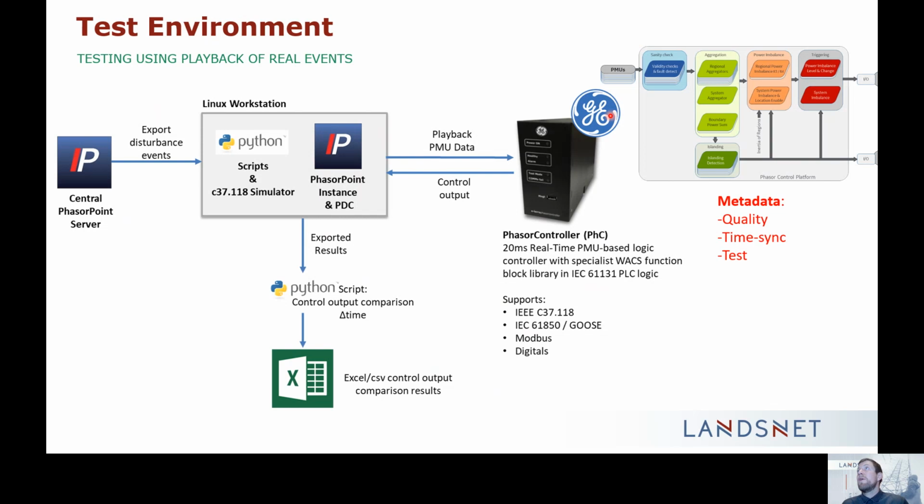And here's a diagram of the modularity of how the control schemes work, going through validity checking, fault detection, then the aggregation phase, islanding detection. The latest one, which I'll refer to a little later in this presentation, is the power balance functions, and then the triggering stage before it reaches the IOs.